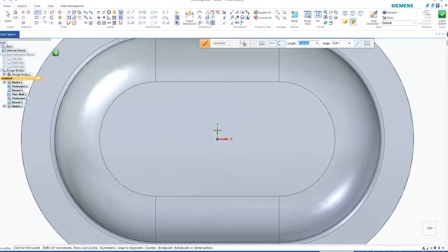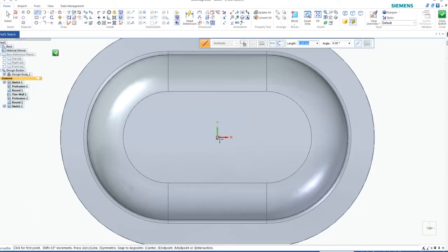Okay, and we'll look straight at it. So the triad, because we built it centrally, is going to tell us exactly where the absolute center is. So we're going to create, first of all, two circles. We're going to make sure that they're in line, and then we're going to change the dimensions using Smart Dimensions. So I want you to click on Circle.